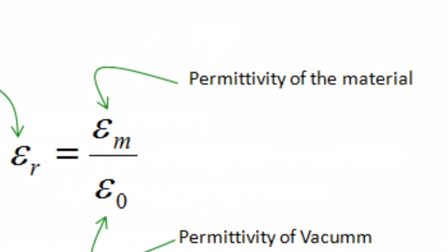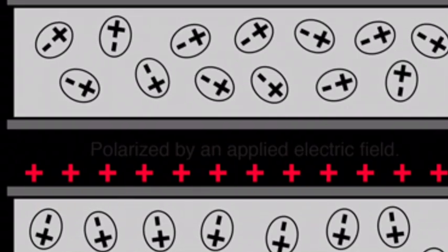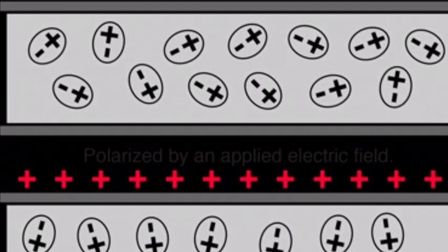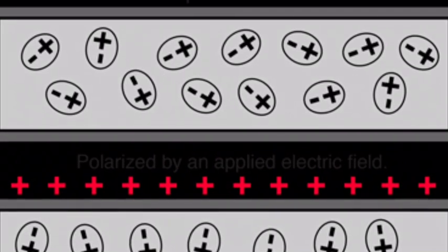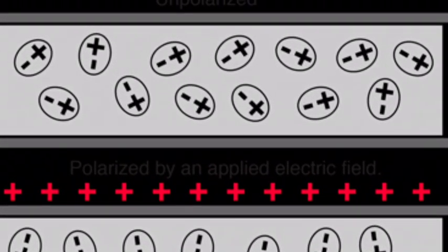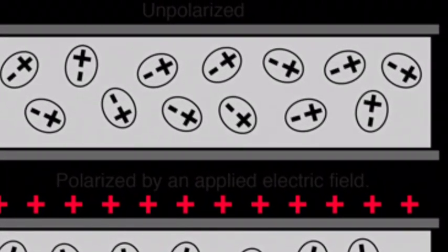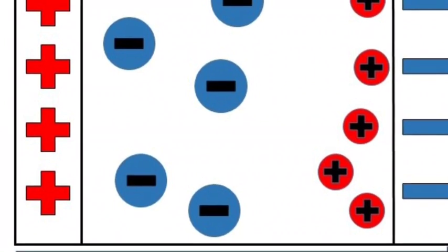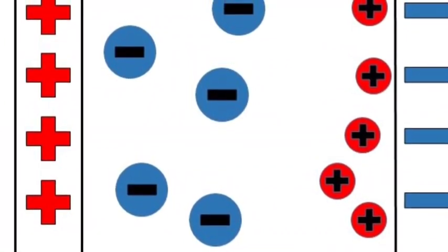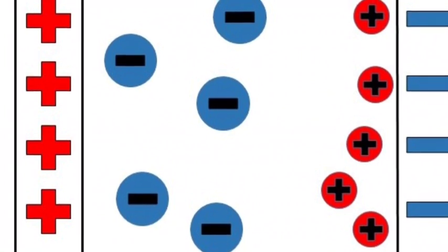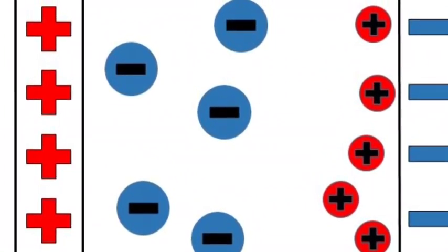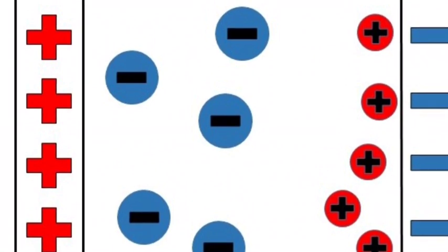This being the dielectric. Now, we've mentioned the permittivity constant, but which material will be the most adequate to be between the plates then? The ideal material is what's called a dielectric. A dielectric is something with a large number of dipoles with the ability to align, because when the capacitor is uncharged, the dipoles aren't aligned. But when there's an electric field between the plates, they align. Each dipole has a small electric field in the opposite direction of the electric field of the plates. But the dielectric reduces this field for the same amount of charge, increasing the capacitance.